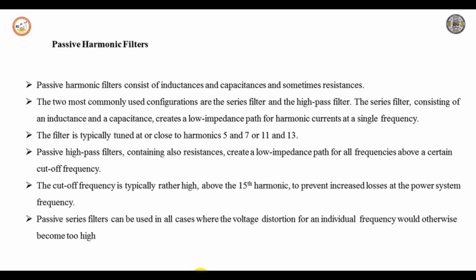Here the injected current compensates the measured current, so the use of such equipment is limited to locations close to the source of emission. Power electronics converters based on voltage source converter technology are more and more used as a grid interface for distributed generation. Examples are the inverter with micro CHP, or the solar power, full power or partial power inverter.